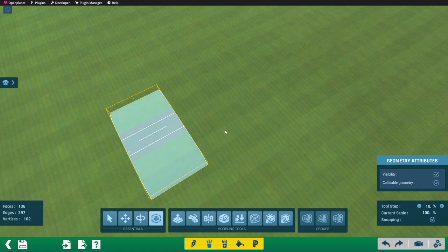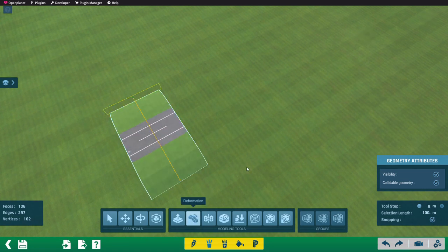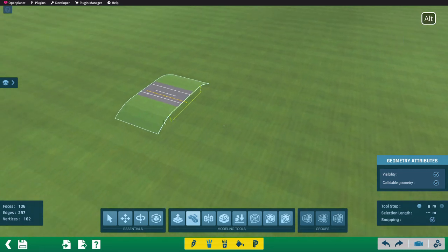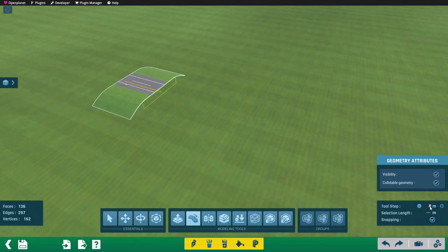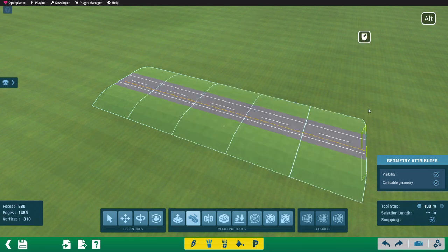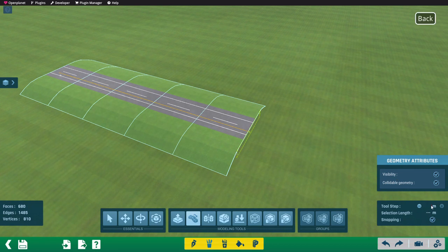This item is currently 32 meters long. We calculate how long in meters a 90-degree turn with 100 meters radius would be. The result is 100 times pi divided by 2, which is equal to 157 meters. We divide the 157 by 6 because 15 degrees fits 6 times into 90 degrees. The result is about 26 meters.